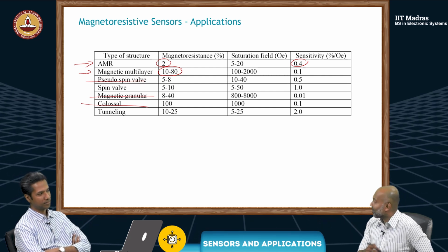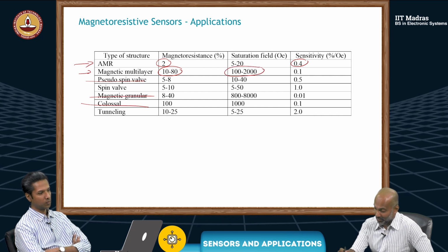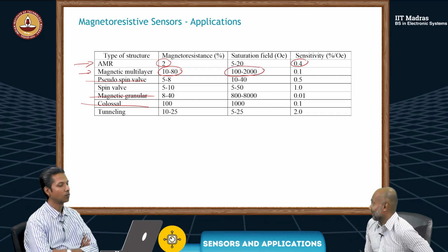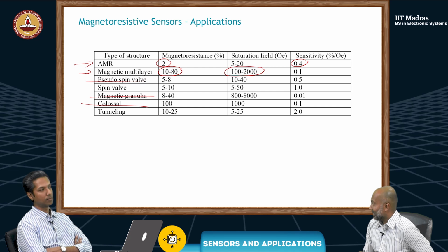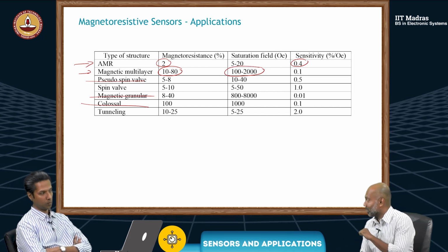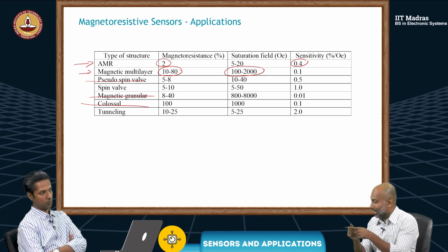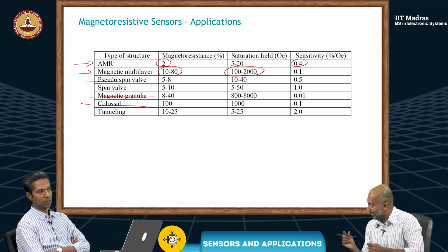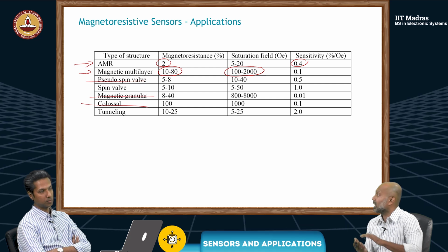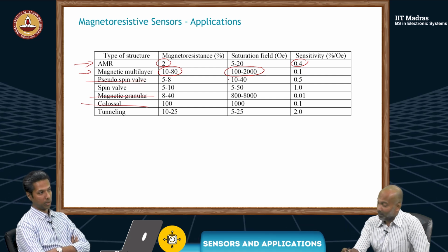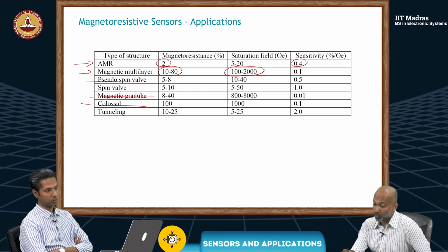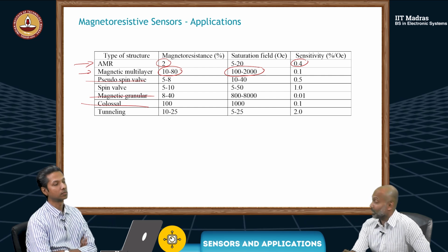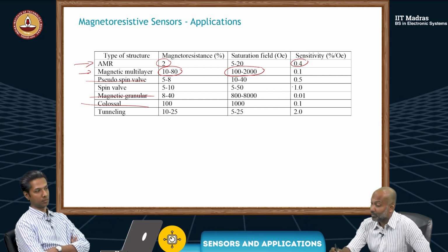See, with the magnetic multilayer, the problem is the saturation field. It's very, very high. Right? When we talked about spin valves, we said the layers are perpendicular and they can very easily move with small fields. But here, because they are multilayers, you need to apply more. So this goes up to 2000 Oersteds compared to the 20 Oersteds of AMR. So that sensitivity is even lower than...